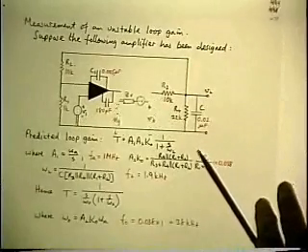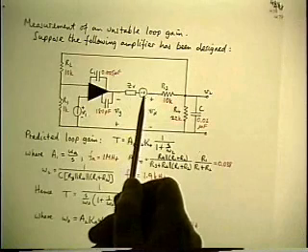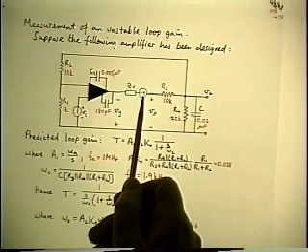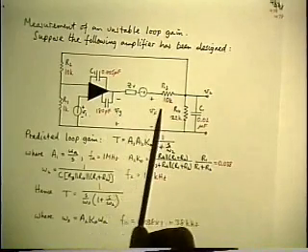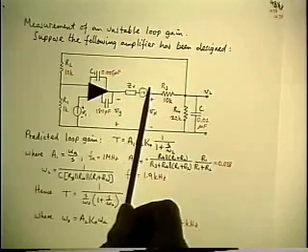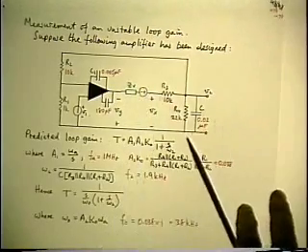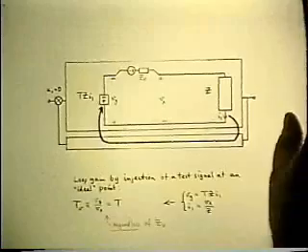So now, at the same place, I inject my test voltage source with the AC clip-on current probe, and I make sure that my measurement probes are on opposite sides of the combination. And now you see I've set up exactly this condition.